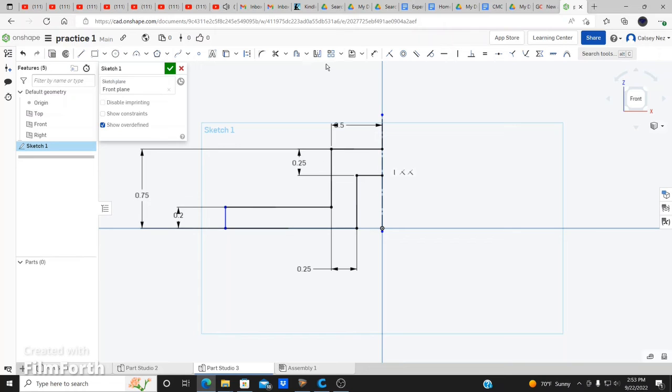Now what I'm going to do is use a mirror feature. I'm going to select the center line. Always select the line because it'll give me the instructions right here. Then select the entities that you want to mirror, which are these lines that we created. I'm going to select them one by one, just to slow down, and also it's going to be a slow task. If you do it too quickly, it will work okay, but then you might mistakenly select the other entities right away. So we don't want that to happen.